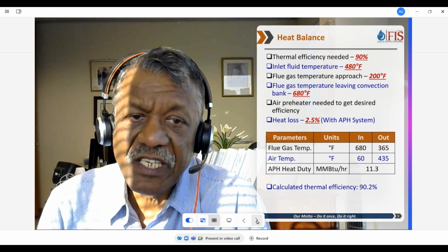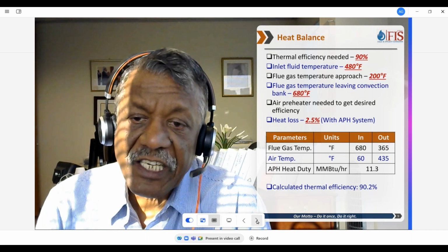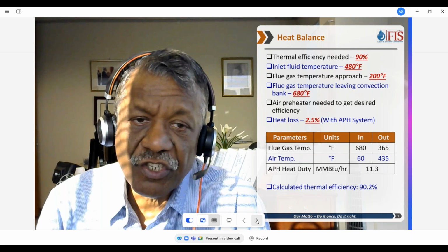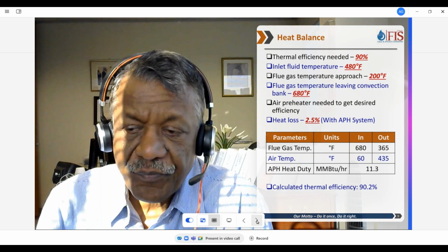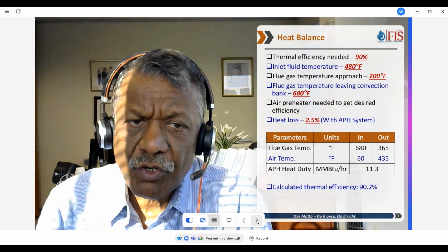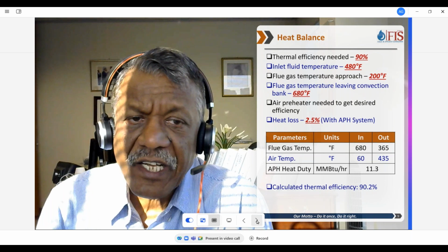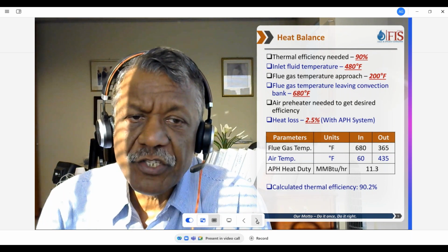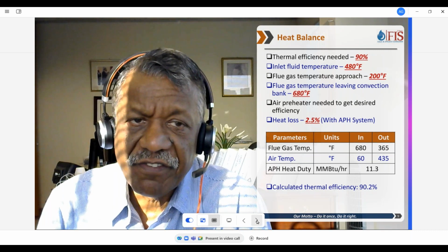The reason we did it was because we had to put an SCR unit, selective catalytic reduction unit, and 680 is the perfect temperature for the SCR unit. So we kept that approach, and then to get 90% efficiency, we have to bring the flue gas temperature down to about 365 or 350.